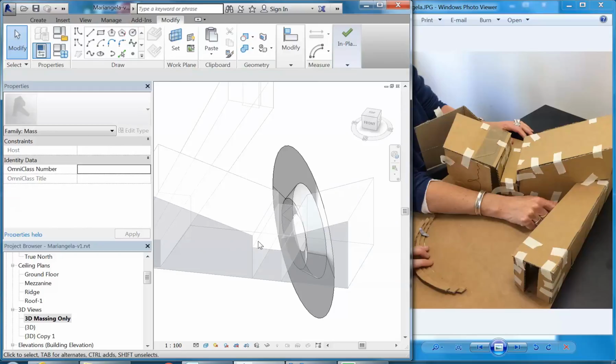When you select more than one shape, Revit thinks that you're trying to do a different modelling operation. So you can actually do every modelling operation that you're used to with solid modelling. In other words, extrusions, blends, sweeps, revolves, swept blends, and a lot more besides. You can do lofting, in other words, sweeping with changing profiles, and lots of other things. So it's a really powerful modelling system, but the way you access those tools is by selecting combinations of shapes.